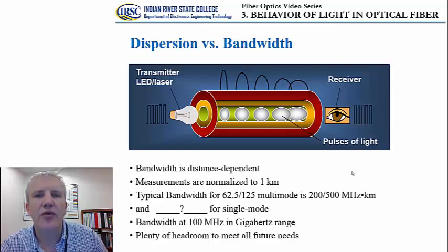And then we also dived into the concepts of attenuation and dispersion, two main causes of signal loss in the optical fiber. We have described attenuation and important causes that are associated with the attenuation, namely scattering and absorption. We also talked a little bit about bends. We classify them into macro bends and micro bends.